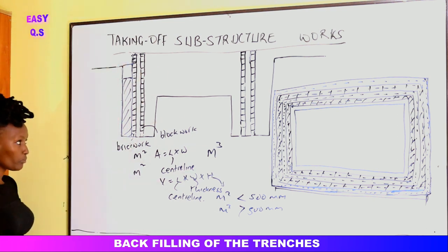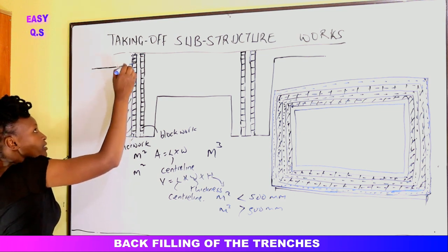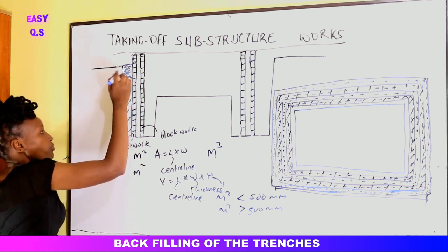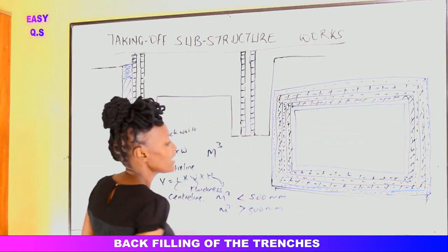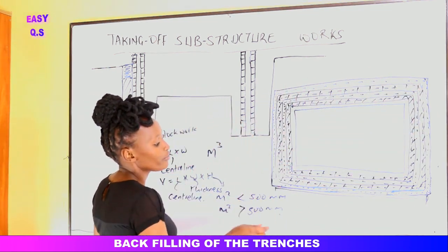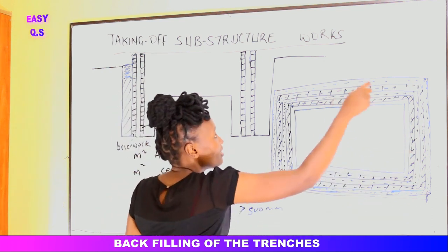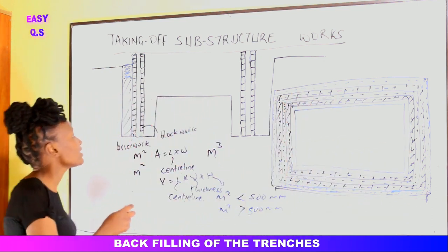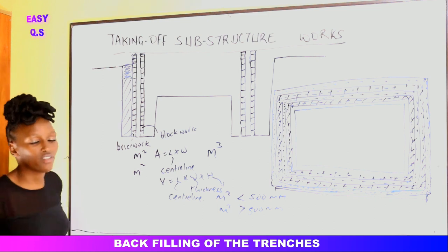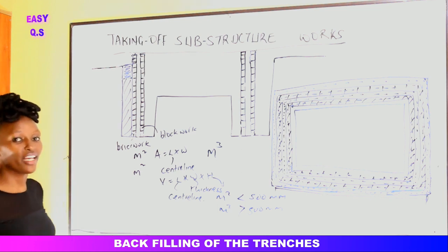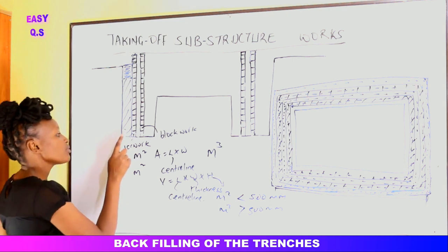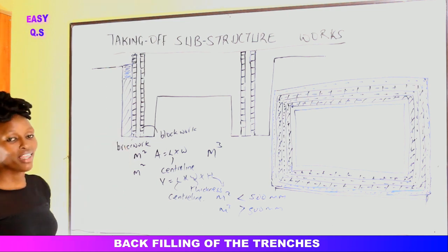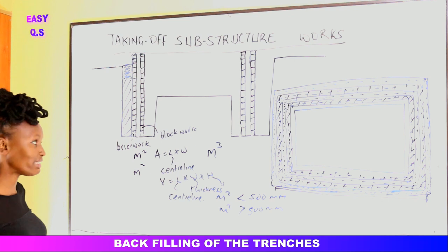Alright, so to measure for this volume of soil going all around the building, we shall take still the center line for the trench outside, then we shall multiply it by this height, the height of the vegetable soil. If we had removed the height of 150, that one shall be the center line for this spread on the outside, then we multiply by that height.